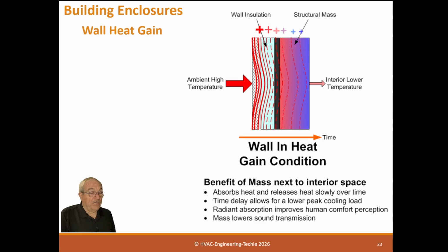So you have to be really careful about this. You have to design your walls to not be too thick, because that could be a problem. You don't want the wall so thick that it gains the heat from the previous day and releases it right at peak temperature the next day. No, you want it in between that. So about 8 to 10 hours is what we want. That's normally a 6-inch wall. So when you get to 10 or 12-inch walls, you have to figure that out because you get too big.